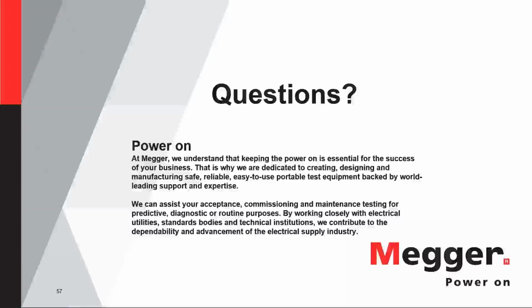Thanks, Emilio. Next question: if the result is in the unacceptable range, will the instrument automatically reject it? Both ASTM D1816 and D877 ask you to calculate the range, which is the difference between the min and the max, and the standard deviation as part of the standard test result. What it looks for is the range criteria.